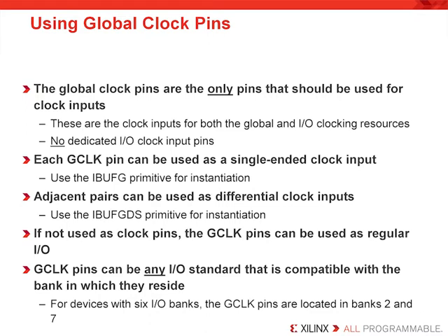To help with planning your I/O pin layout, I recommend that you use the Architecture Wizard as well as the PlanAhead tool. When using the smaller density Spartan-6 devices, there is 1 I/O bank per edge. You should also note that the global clock pins are in the same I/O bank.